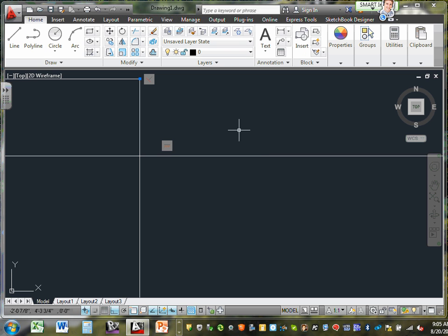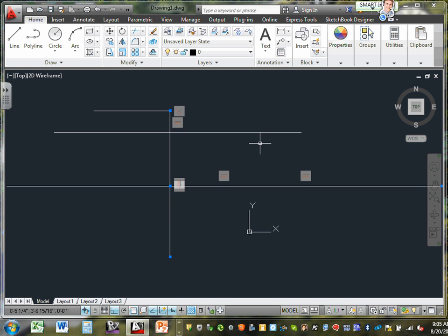Well, before we go into even view, if you type Z, enter, and E, enter, it will zoom out to see everything as far as it can go. So get used to it: if you get lost and you don't know where you are, type Z and hit enter. That's like zoom all. Z, enter, E, enter will get you to look at everything. I found it to be very helpful when we do electrical design. Z, enter, E, enter.